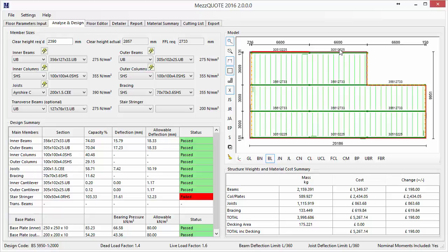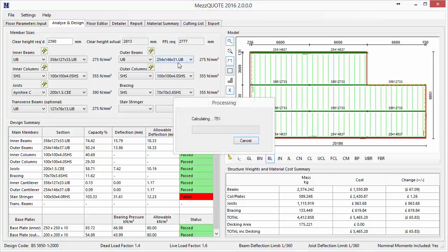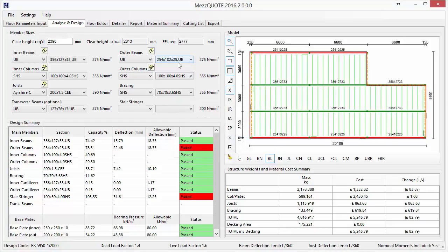The outer sections, the outer bays, they're not actually taking as much load, so if we optimize those, normally it will allow us to choose a different section. In this case, the section was actually okay, so it hasn't needed to change it. If I go to the one below that, I can go to 43, which is obviously less economic, and if I keep going down, soon I get to a section that fails, and it's failing on the outer edges.